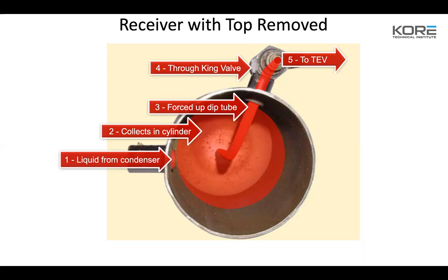And the reason why we need to have some fudge factor there, I call this the extra liquid in the system, is because that TXV is always throttling back and forth. And what it requires on the inlet side of that is that solid column of liquid. If it's throttling at a massive rate, like coming out of a defrost, or you have the system down and you're bringing it back online and that thing throttles wide open,